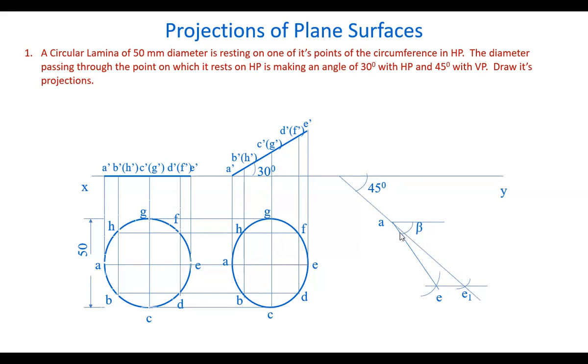So once you find the apparent angle, we reproduce the same top view here by taking these 2 points as reference. From A, take AB length, and from E, take EB length, and draw 2 arcs. That's how you get point B.